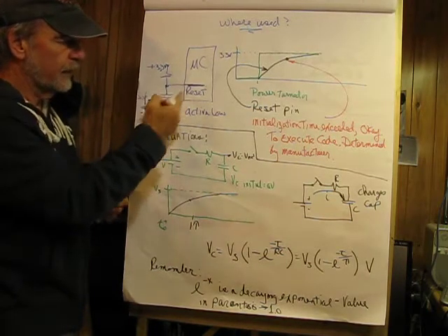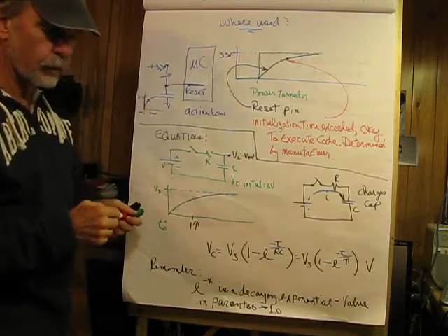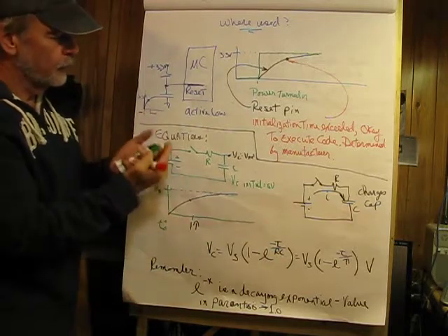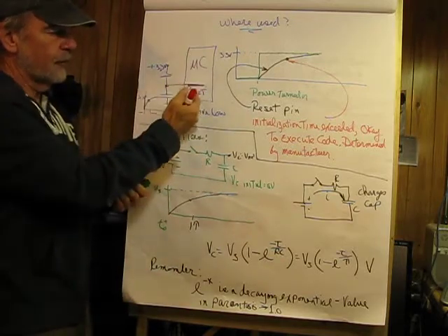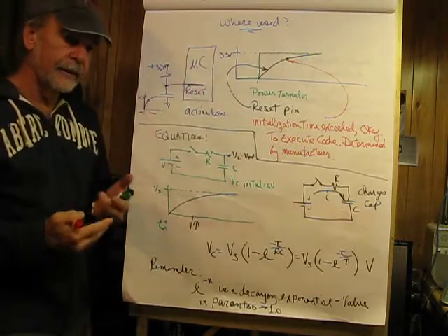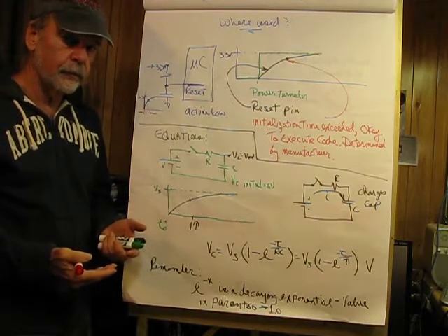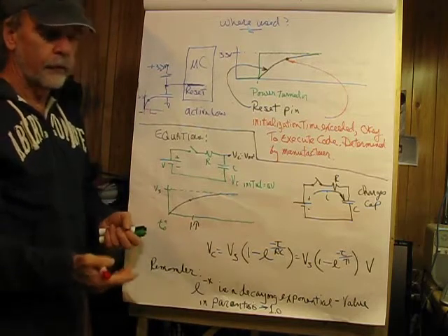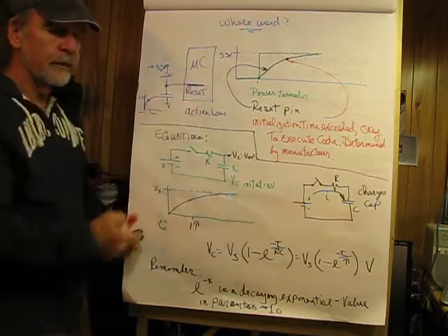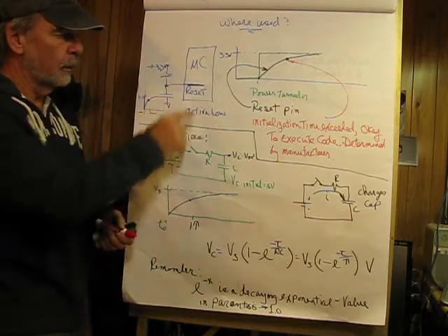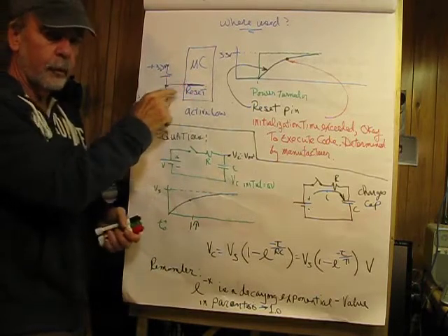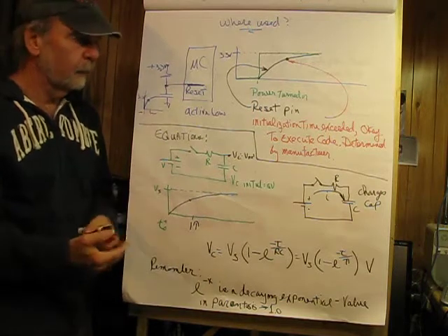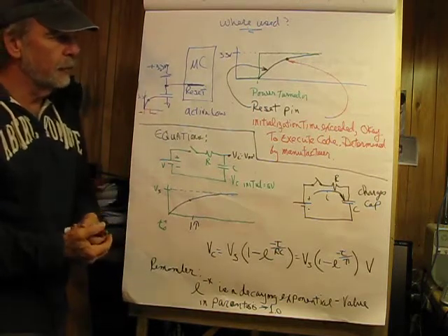is there's stuff that has to go on inside of a microcontroller before it can start to execute code. For example, a charge pump has to set the whole block of silicon that this thing is laying on down to about negative 0.7 volts. Otherwise, the transistors won't work. Further, registers have to be initialized in here. For example, the program counter or instruction pointer has to be set to the first instruction in the program. Makes sense? And it takes time to do that.